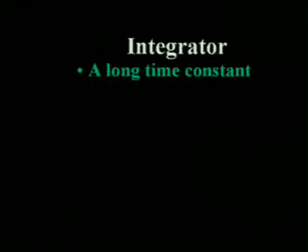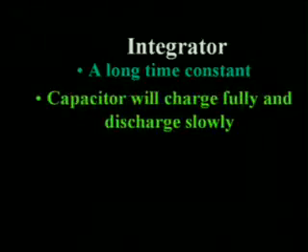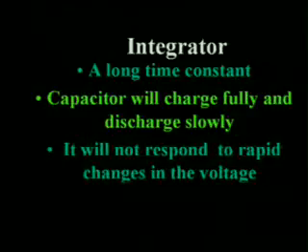So, now come to the integrator part, and this integrator part is meant for vertical sync. It has the long time constant, the capacitor will fully charge and will discharge slowly, and we have already told you the capacitor will not react with DC values.